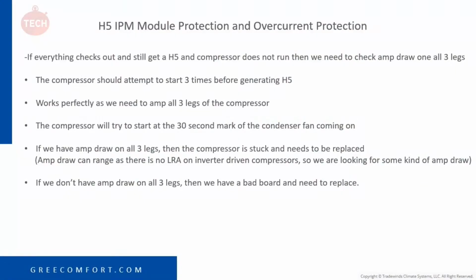What I tell people is to get your amp clamp on one of the compressor wires. After a hard reset, turn on power. The condenser fan comes on right at 30 seconds. We're going to be watching for an amp draw on the leg you have it on. If we have amp draw on all 3 legs, then the compressor is stuck and needs to be replaced. Amp draw can range. Again, there are no locked rotor amps on inverter-driven compressors, so we're looking for some kind of amp draw.